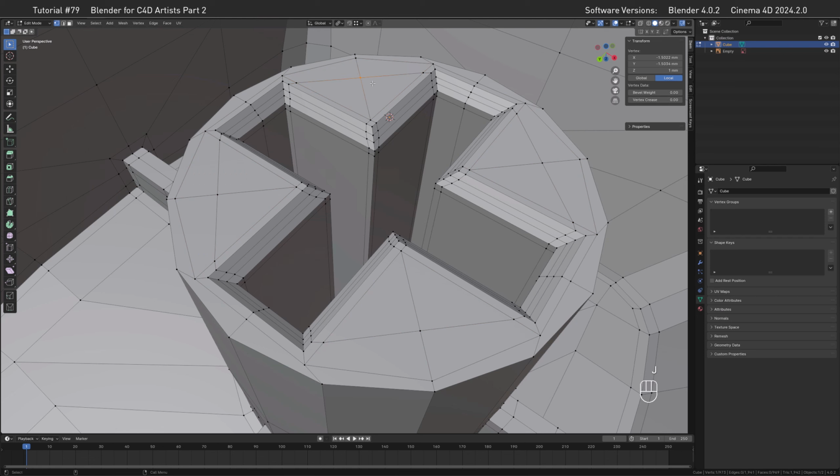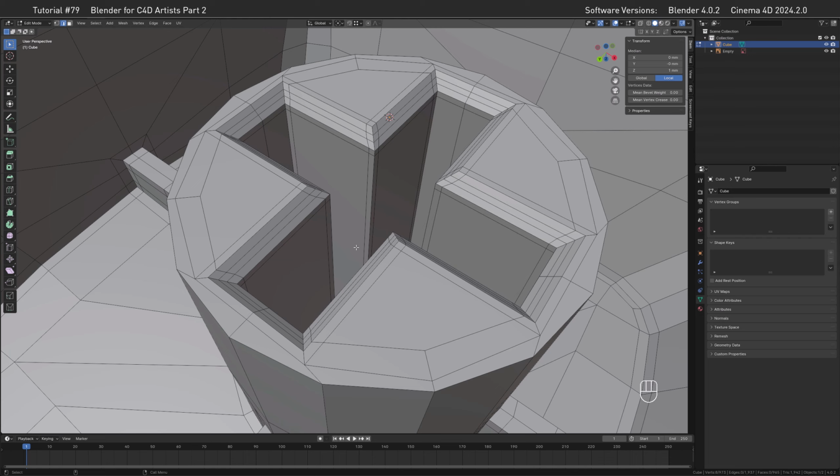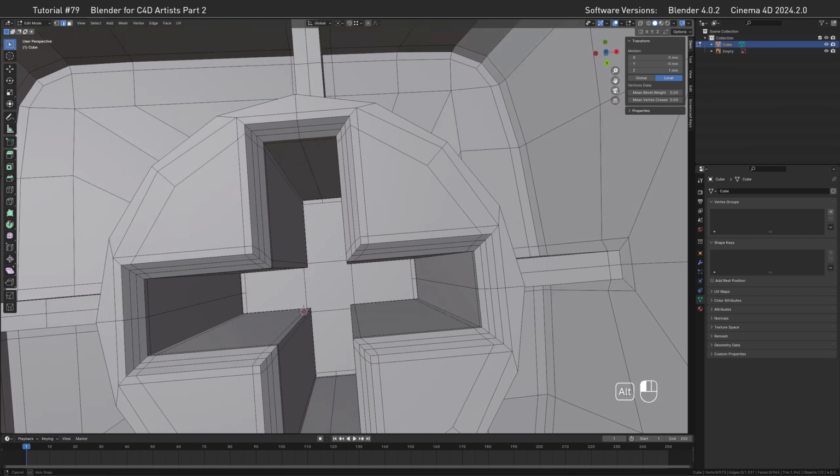Right, so then select all of those points and scale them outwards. We need to go back to bounding box center and then scale them so they look roughly okay. And then last but not least, we need to go into edge mode, select those edges, and then dissolve them. Here we go. Alright, some last finishing touches here before we are ready and can showcase our nicely modeled keycap.